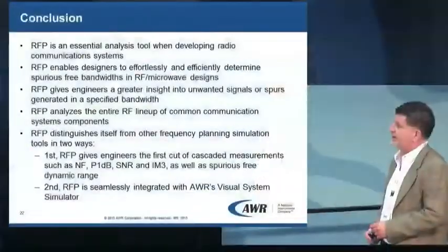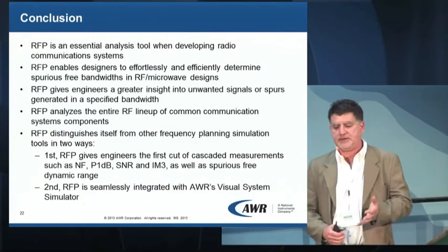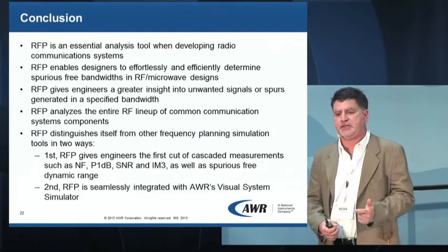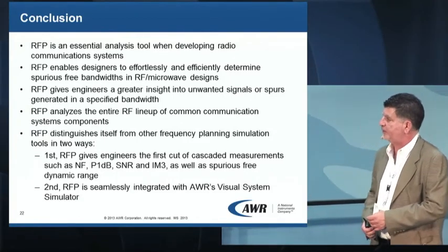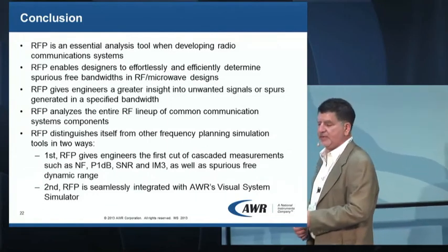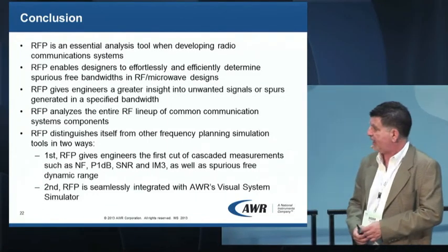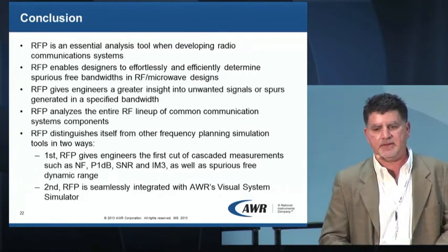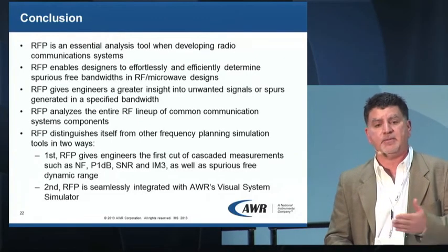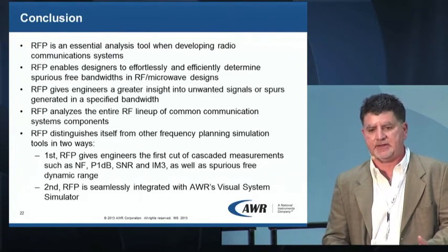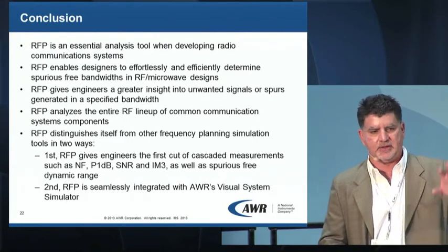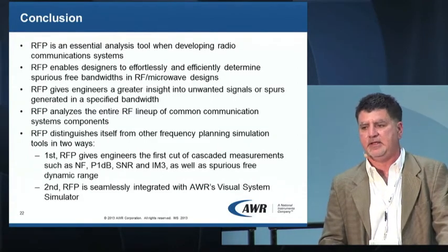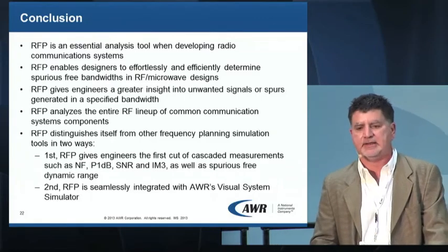So in conclusion, RFP is one of the essential analysis tools when developing a radio communication system. It's fast and efficient, and you'll have a first go at calculating the noise figure, P1dB, and signal-to-noise ratio, and ultimately the tool is integrated with the AWR design environment and VSS. You can start replacing components with Microwave Office circuits as well in the VSS environment. So you can start at the very highest level of abstraction, your RF architect, all the way down to the actual design of that component at a circuit level.